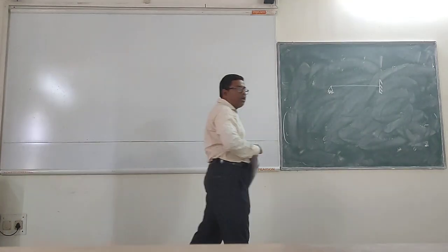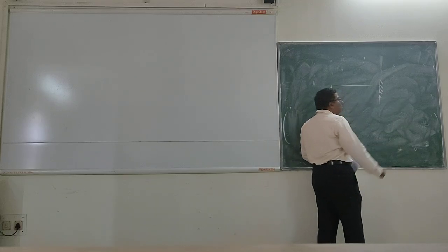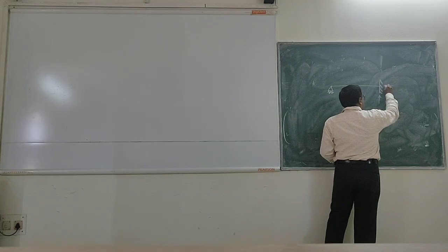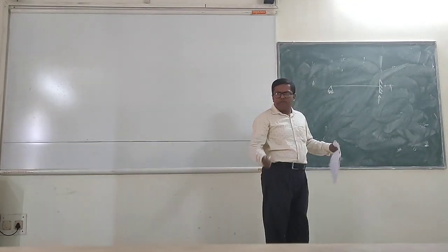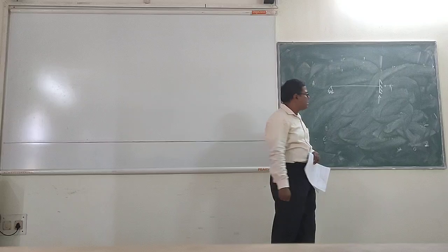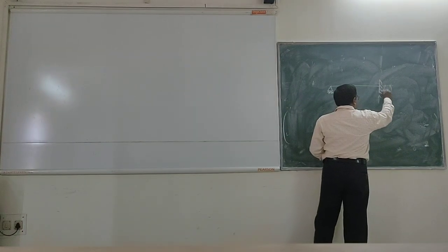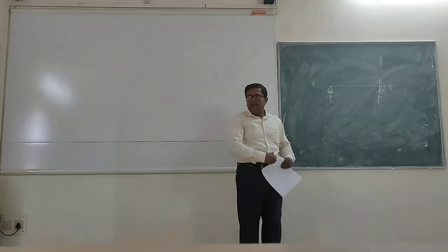However, in this case, there is a vertical reaction which is unknown. There is another reaction which I can neglect, because horizontal forces don't come as such if there are only vertical loads on the structure. And there will be a moment in the structure, as well as a vertical reaction at the supported end.